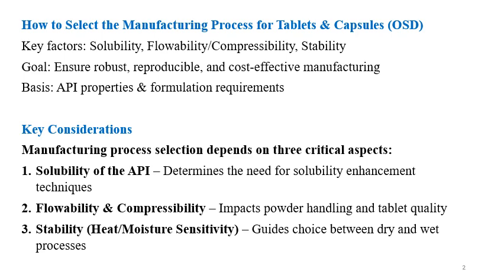Flowability and compressibility impact the powder handling and the tablet quality. Also, they impact the weight variation in the tablets and capsules. Stability towards heat and moisture, sensitivity to heat and moisture, guides the choice between dry and wet processes.